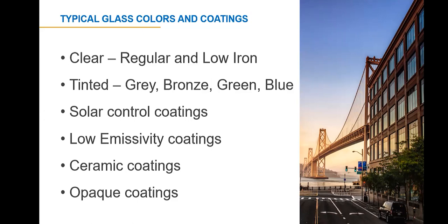Traditional reflective glass has a mirror-like appearance and reflects and absorbs a major portion of the sun's direct short-wave radiation. The degree of reflectivity is dependent on the type of the coating and the orientation of the glass. The use of reflective glass is most popular in commercial glazings as it provides superior solar control performance to clear or tinted products. Low emissivity coatings are traditionally clear and are designed to reflect long wave radiation.